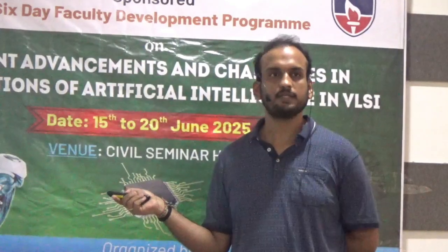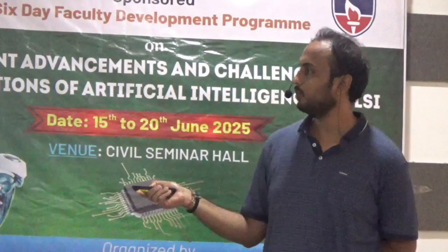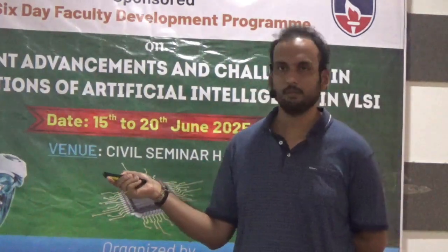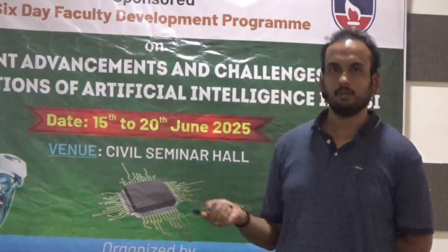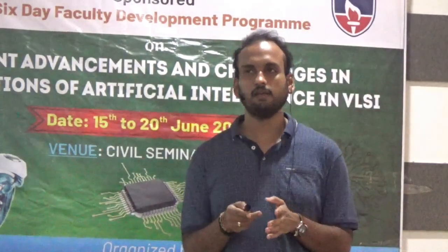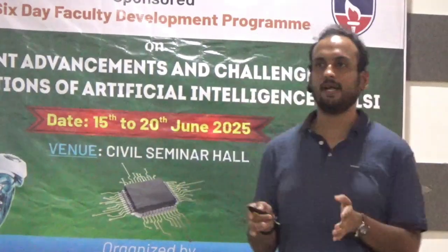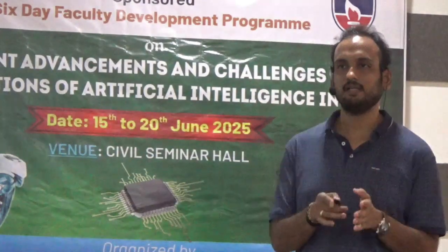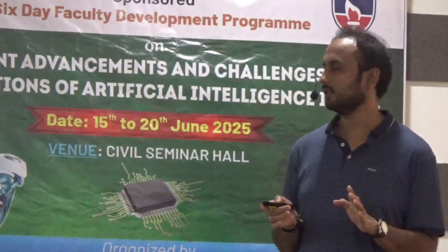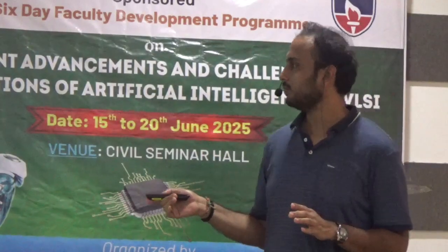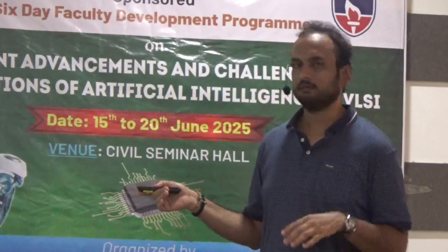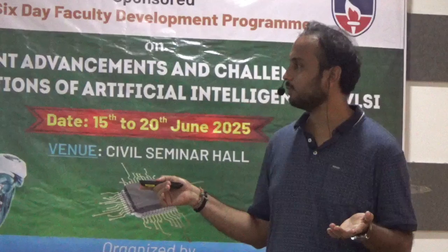So how can we increase the data rate? One way is more bandwidth. You can increase the bandwidth, but that is not something allowed, because if you work with wireless communication for mobile, we have different bands, and each band has different channels, and each channel is a fixed bandwidth. The bandwidth you cannot change. So you have to define more complex modulation schemes.